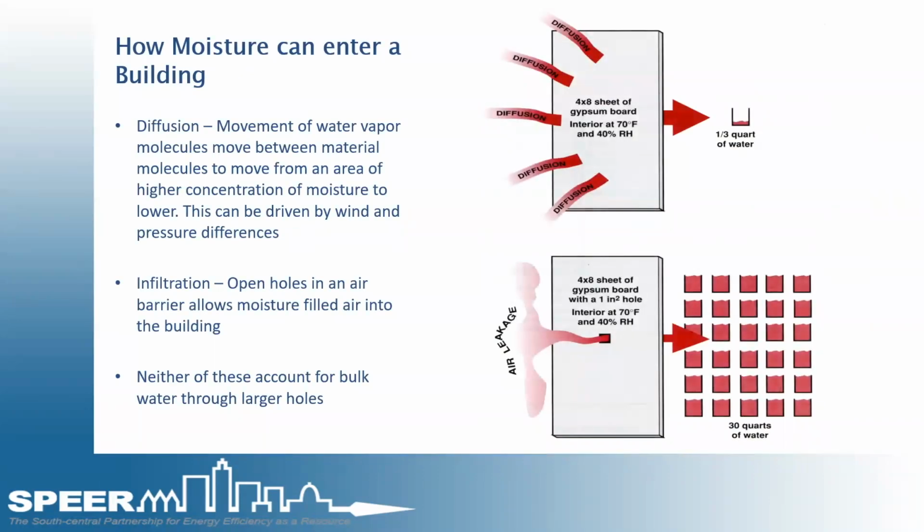The reason why a lot of this is important, and a lot of things that we look at, is how does moisture get into the building? We just went through the air barrier part of it and looked at a few things that seem minuscule. It seems picky and petty. You see punctures with nails. You see punctures with staples. You see little gaps that aren't stapled. You see overlaps that aren't stapled, and they leave gaps.